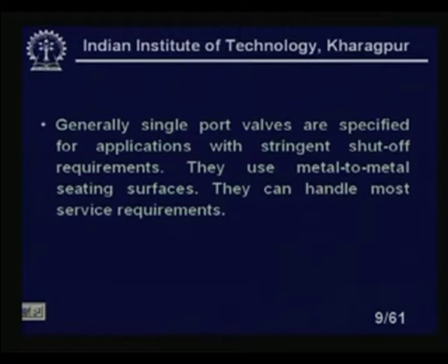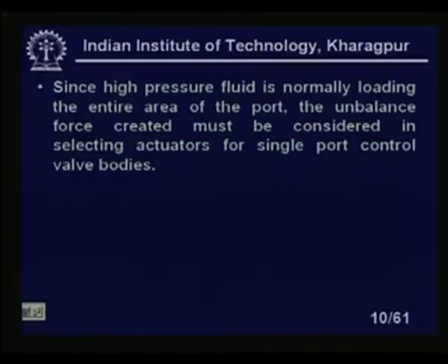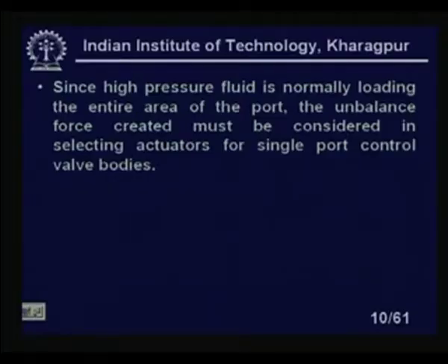They use a metal to metal seating surface and can handle most service requirements. Metal to metal surface means the seat is metal as well as the plug. So they handle most service requirements, that means corrosive service and high temperature can be withstood, though nowadays Teflon can also withstand a high temperature, but not as high as metals like steel. Since high pressure fluid is normally loading the entire area of the port, the unbalanced force created must be considered in selecting actuators for single port control valve bodies.